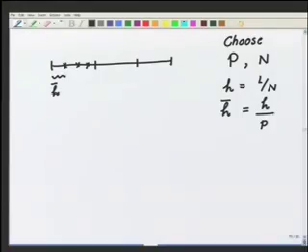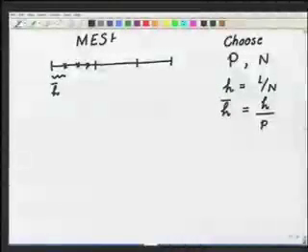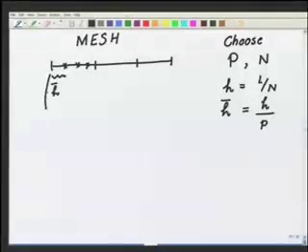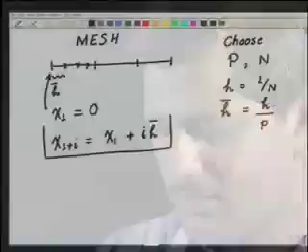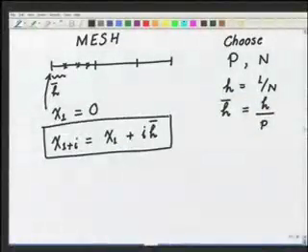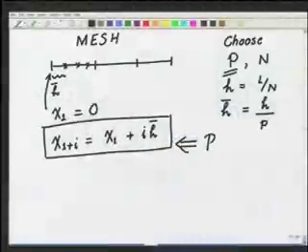Okay. So how do we now go ahead and make the mesh? So I have to make the mesh. So solution nodes, so I start with x1 is equal to 0 or the given value, and then we say x(1+i) is equal to x1 plus i h bar. This will give me the mesh. So once I have the mesh, then what do? Then we have to construct the shape functions. The mesh generation generally falls under the pre-processor.